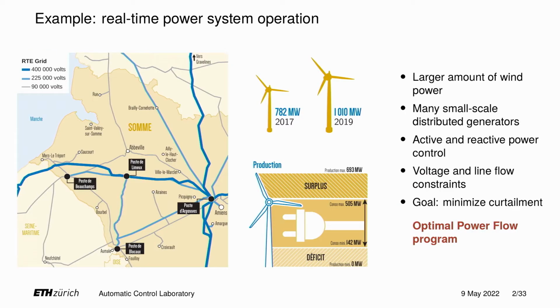So again, in just less than a minute, the problem that's been given to us was to make sure that the electric state of a part of the transmission grid, in part of France in this case, was safe, maintaining voltage and line limits, even if in the same grid there was a severe connection of new sources of renewable energy. And the new sources of renewable energy are fluctuating, and so you need to respond to what they do. You don't know how they're going to fluctuate in time. And so you need to set a lot of inputs, because these come in the number of thousands or hundreds, in order to make sure that the state of the grid satisfies your specifications.